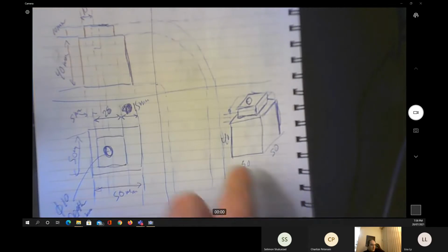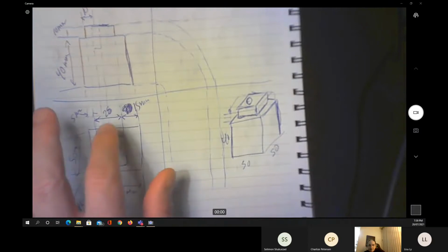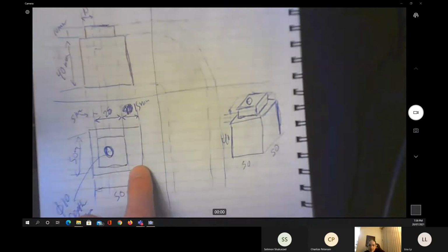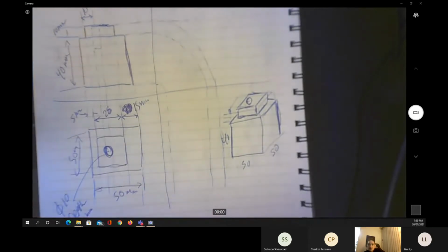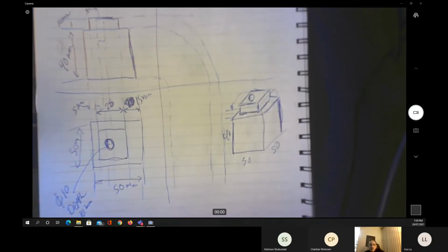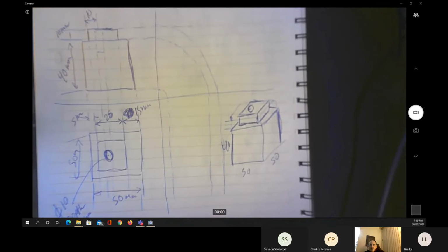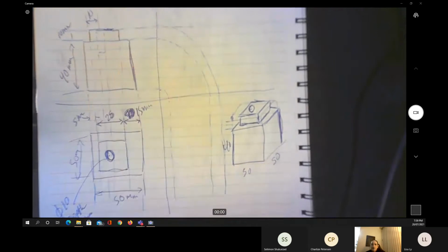It's only going to require to take a look at the top, make the offset lines. You need to go in a circle, then you need to go in a straight line to clean this area, because this area is wider than that. Choosing the cutting tool, you already had the hint, because the diameter of the hole is 10 millimeters. So you can use a 10 millimeter diameter to do the cut. That's it. This will be your exercise for the next session.